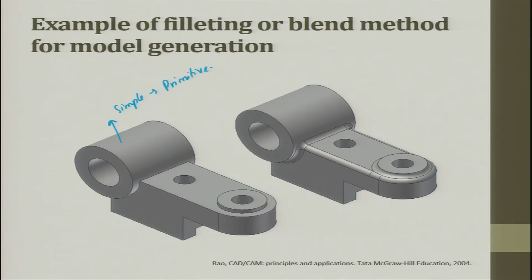These primitives are chosen and placed at locations. But when these primitives are placed and butt against a flat one, it is always necessary to have filleting done such that these points are not the stress concentration points, and you can keep continuing this.